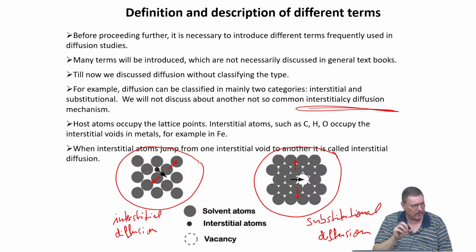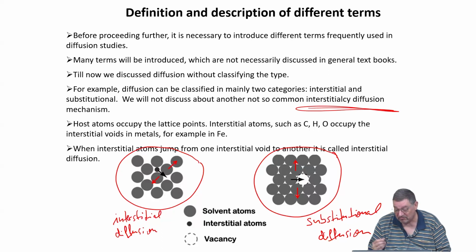And then the mathematical description again is different, because a vacancy can more easily jump than any atom, whether it's in the interstitial lattice or whether it's substitutional. And so then this is kind of a coupled diffusion process. It's not very important for metallic materials, but if you think of semiconductors, then this is a mechanism which needs to be taken into account.